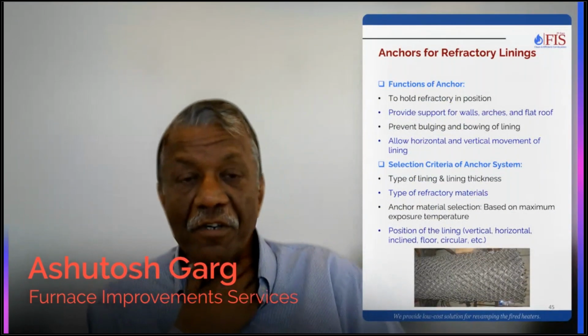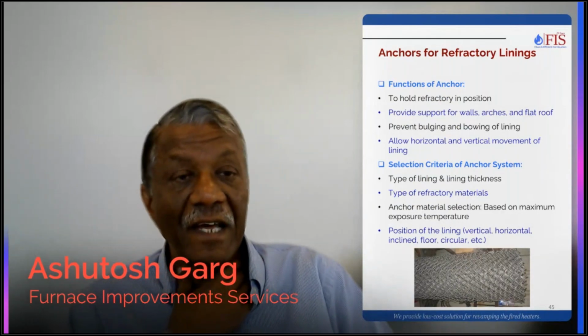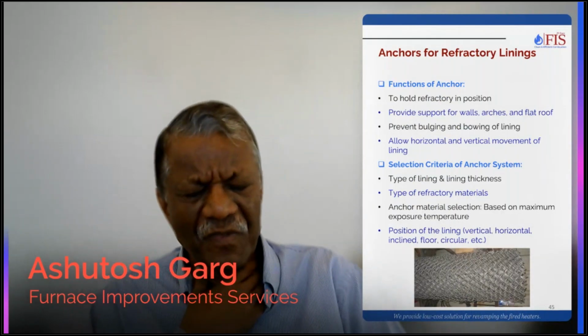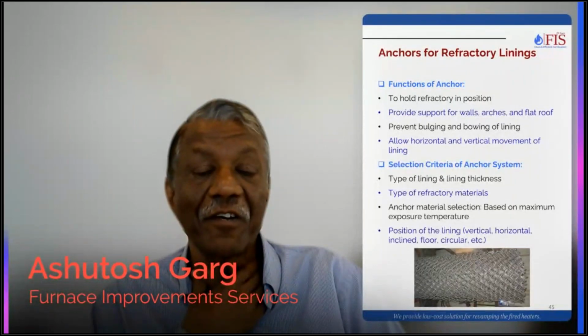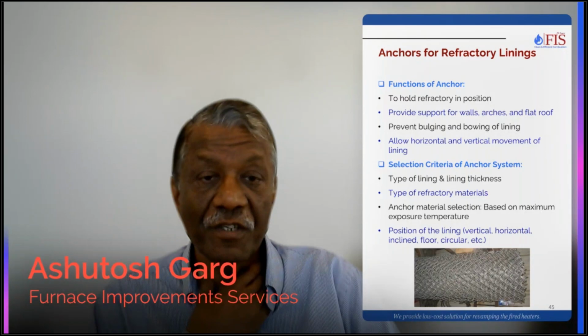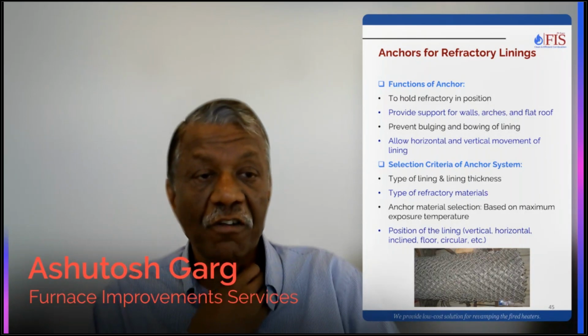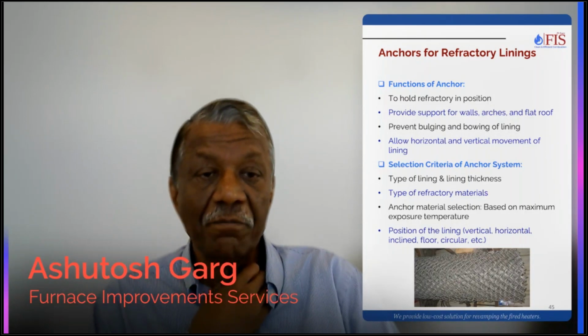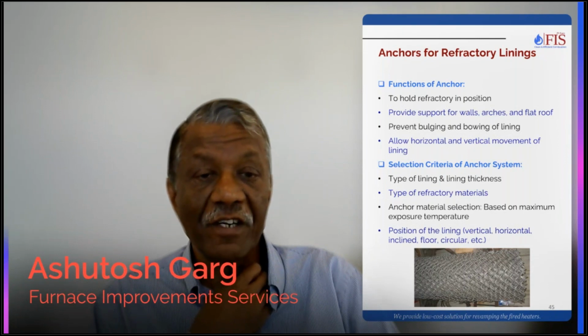Another important component in lining, especially in castables, is anchoring. Anchoring is supposed to hold the refractory in position, provide support for walls, arch, and flat roofs, prevent bulging and bowing of lining, and allow horizontal and vertical movement of lining.